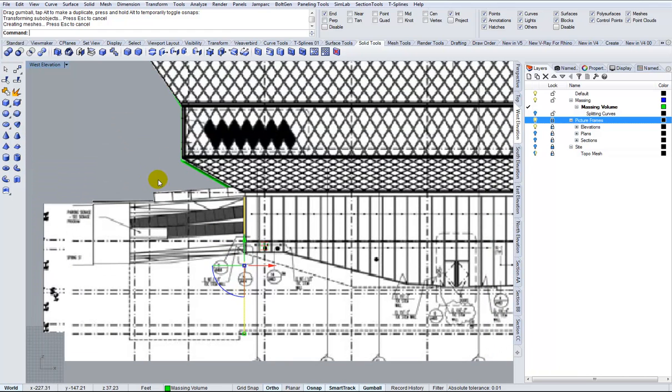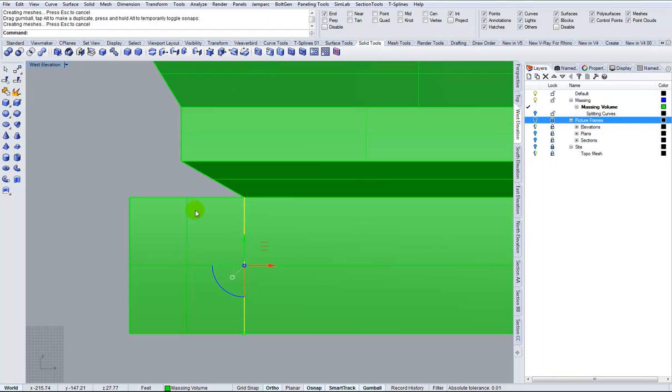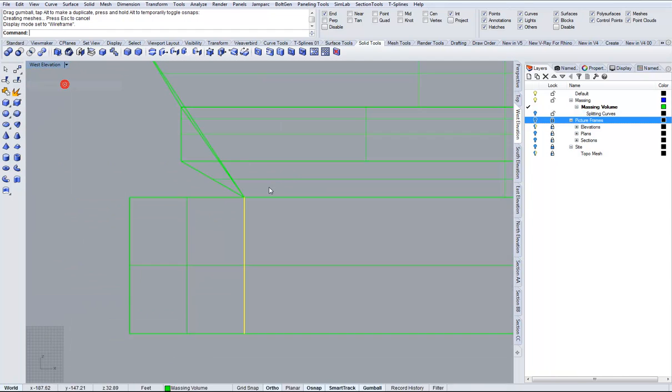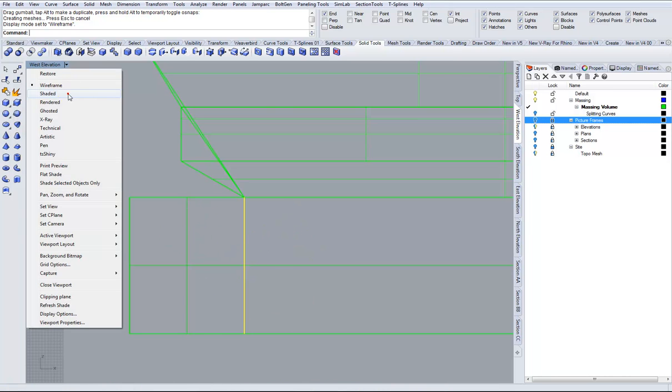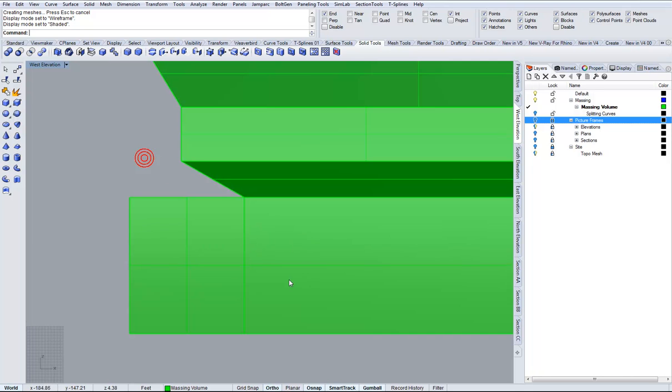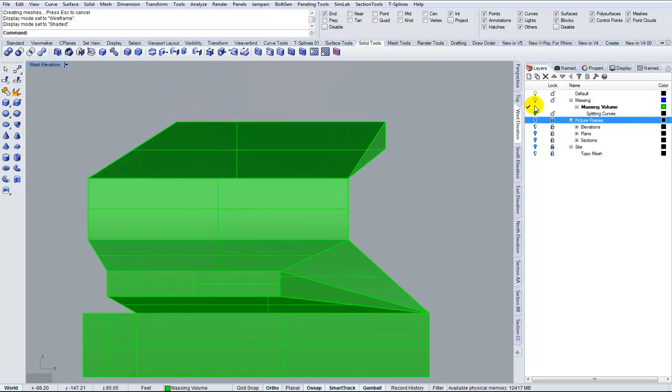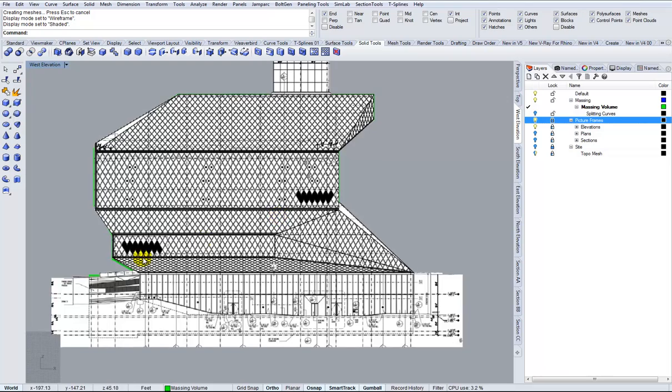I'm going to take it and then drag it back out. But instead of just dragging it, I'm going to hold down the control button and make it an extrusion instead. And it'll just extrude that volume out and leave everything else intact. And you can see, if you look in Wireframe, that it's still a single solid. It's not adding another solid to it. So it's pretty clean. And turn my picture frames back on.